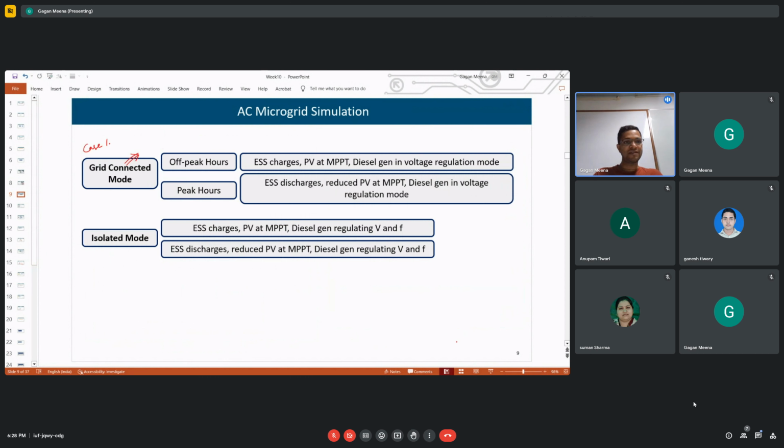So that is why this scheme provides more effective utilization of devices by using this kind of delay mechanism. And it provides improved voltage profile, improved fault ride-through capability and improved transient condition of the system. So first it will identify the operating condition of the grid, and then it will check for the availability of the devices, and then it will assign a master and slave role. So one of them will become master and the other will follow as slave.